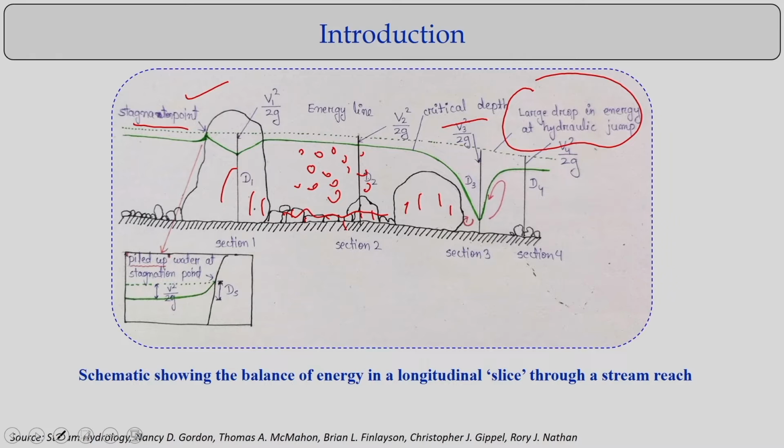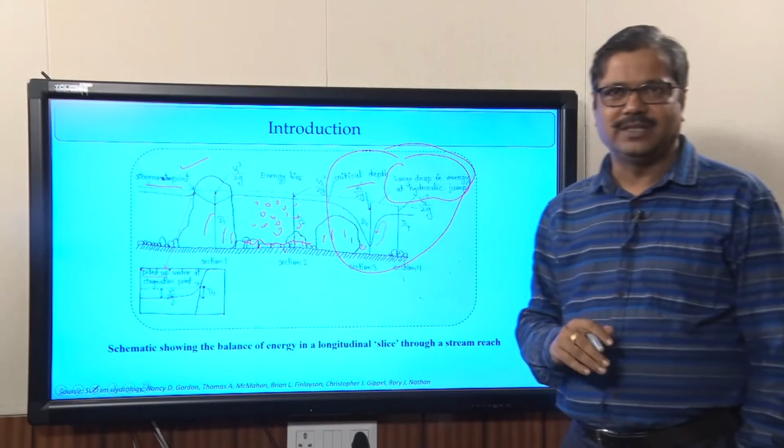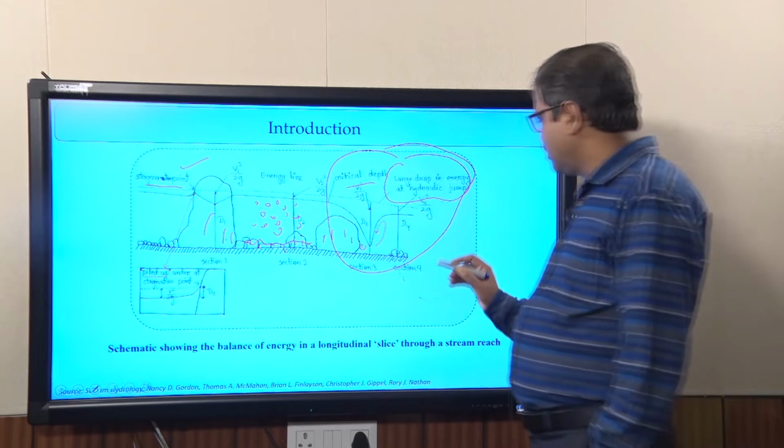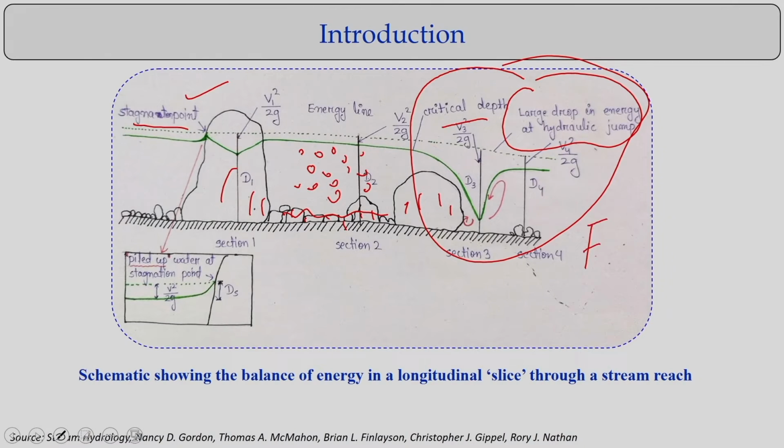But in more detail, we can now look at the critical depth and the hydraulic jumps, which are quite related to each other. Before that, you know from fluid mechanics that the flow Froude number is the ratio between the inertia force and the gravity force. Consider a channel having flow depth h, with v the velocity and A the area of the flow.